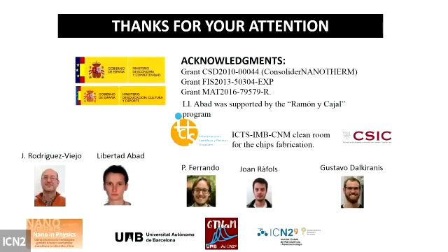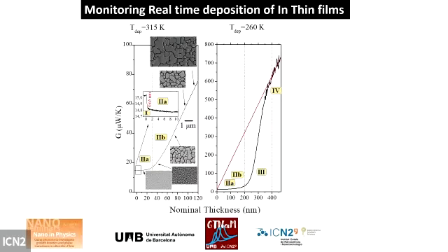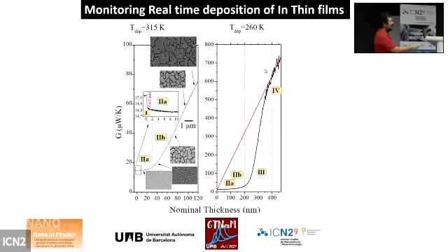The point is, of course, the delta T will be smaller, but we can show you an experience, for example, with indium, that is pretty clear. As soon as you increase the thermal conductance of the film, the noise is increasing. This is essentially because in that methodology we were not changing the power input in the system, and then the resolution degrades as soon as the thermal conductance of the film increases. This is the idea of using that highly conductive silicon.